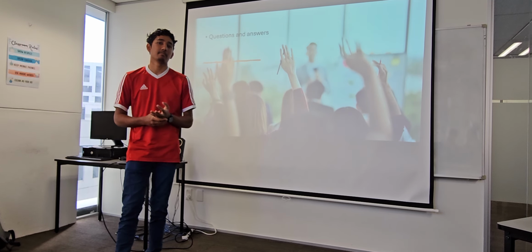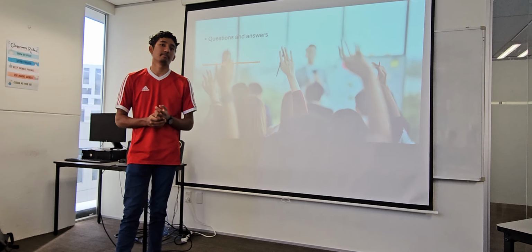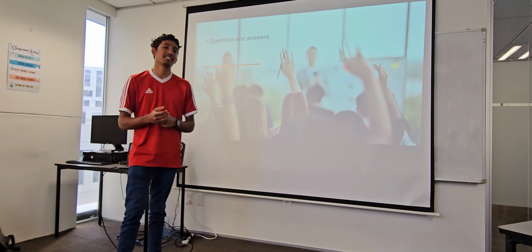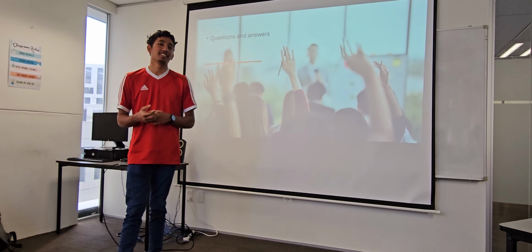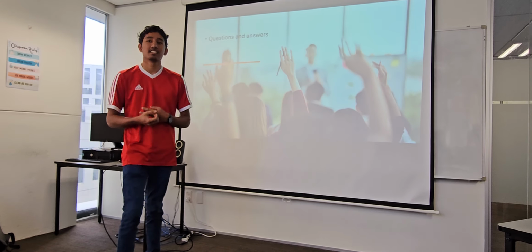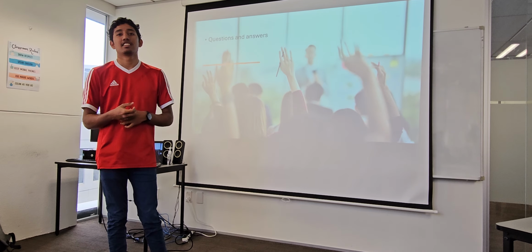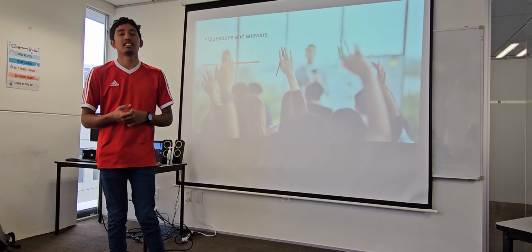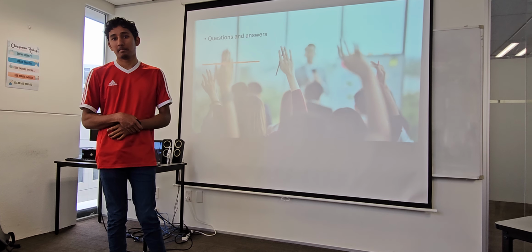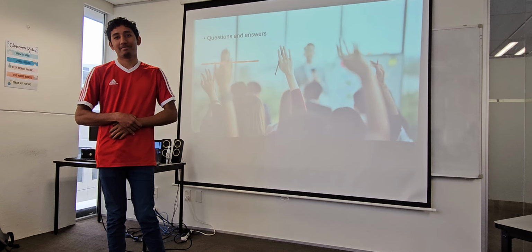Okay, when you are presenting the quantities in numbers with decimals, when you compare all other trades except rebar, there is a specialty when you are showing those particular number values in a BOQ. What is that specialty? What is the specific thing you have to focus on when you are presenting in a BOQ compared to other trades? Only rebar, reinforcement. That's a particular thing you have to be very careful about.